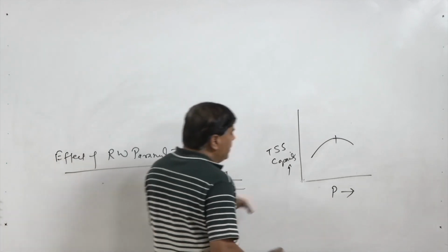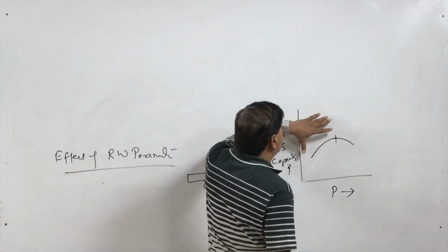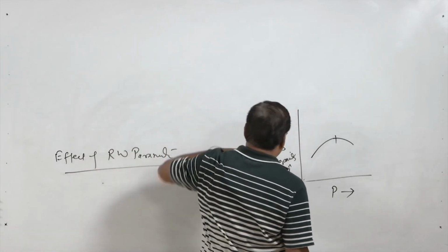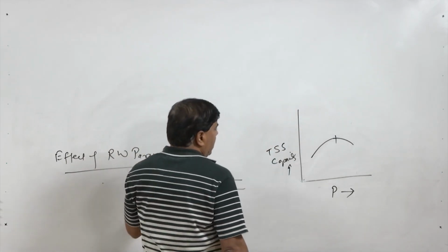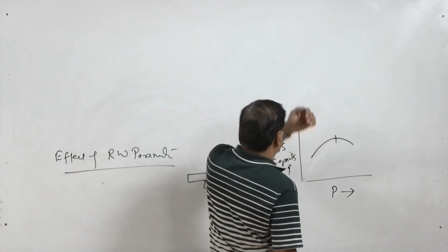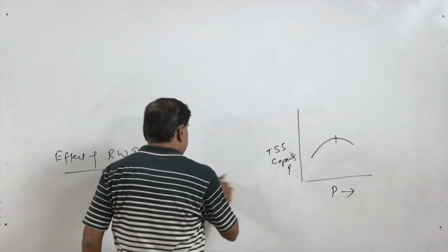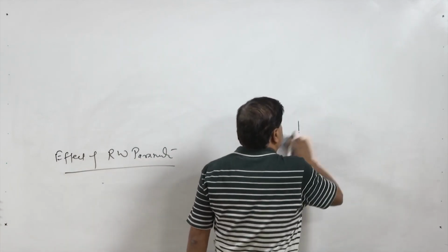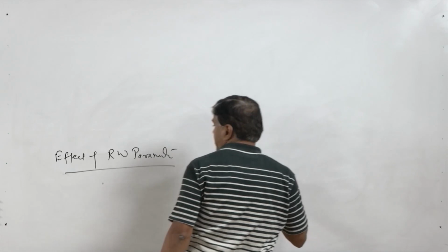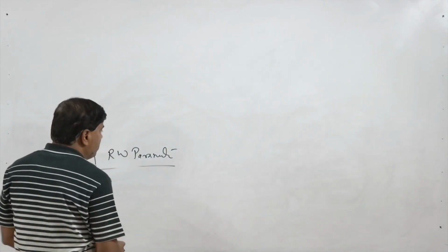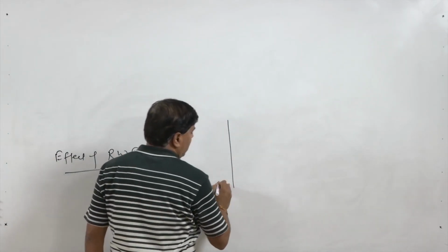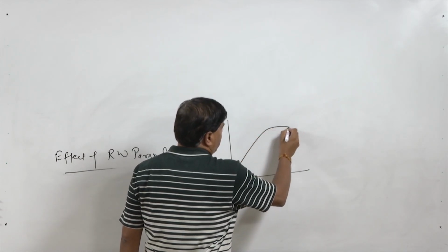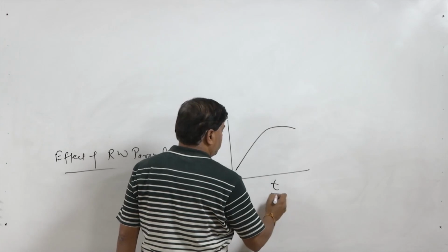But we need to have reasonably good pressure to avoid sparking, and the use of too high pressure will reduce the contact resistance, but a little marginal increase in pressure helps in effective consolidation as well as the solidification of the metal at the interface. And similar to the current, increase in welding time also increases the strength, and thereafter it becomes almost constant.